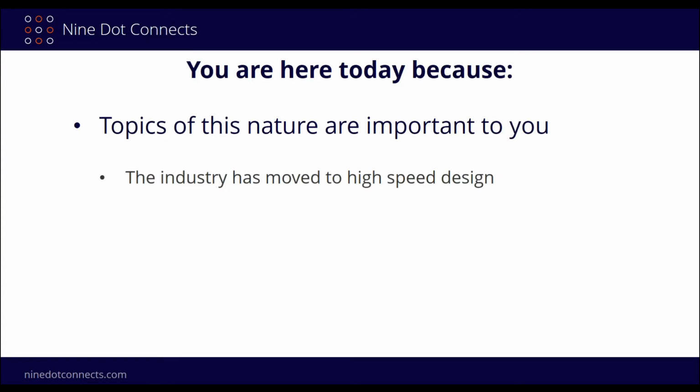It's always amazing how much data we can try to push into an hour here. So you are here today because topics of this nature are very important to you. And let's face it, the industry has moved to high-speed designs, where in the last 10 years we talked about things moving from regular design speeds to higher ones, because we're always trying to push the edge. But it's getting to the point where you really can't design without considering high-speed design. Even if you have a 10 megahertz device using TTL logic, those rising edges are so sharp now that they actually do have higher frequencies, as Sean has mentioned.